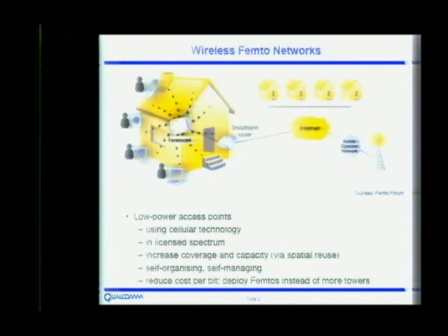Many boxes come with a feature called network listen, which allows the femtocell to behave like a mobile, just for the purpose of getting synchronization and frequency stability. There are also options based on IEEE 1588 PTP based synchronization, although it's not clear that would provide adequately fine resolution.